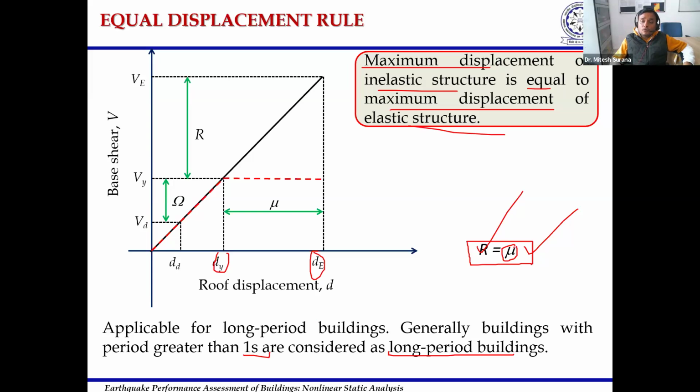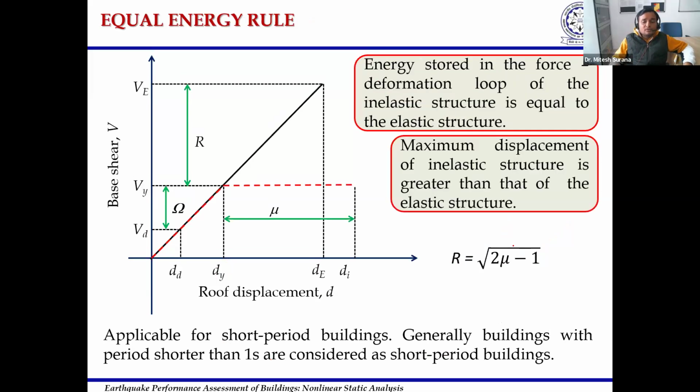And therefore, all the SMRF buildings which we are designing through code will not result in equal ductility, but we are using the equal response reduction factor for all those buildings. So this is where the problem arises in force based design: for all the structures across the design space, we are using the same response reduction factor, but they may not have the same amount of ductility available in them. This is the first important thing that we need to understand, that this is a particular problem related to force based seismic design.